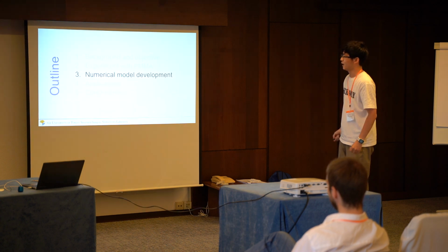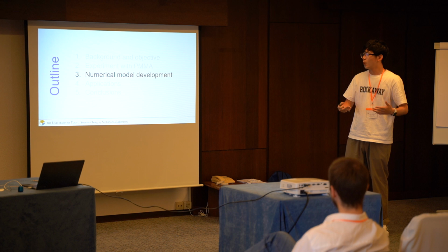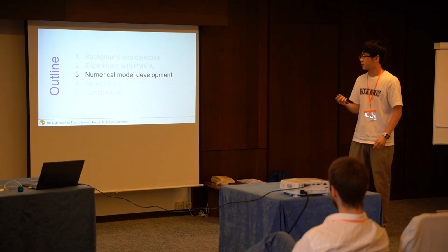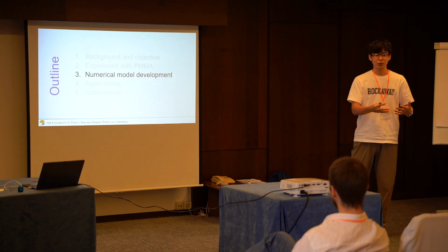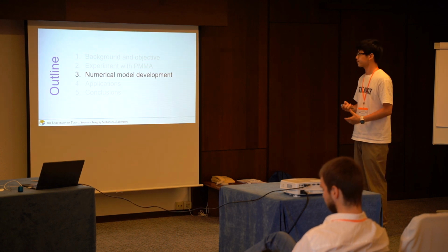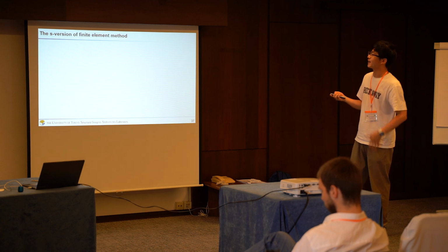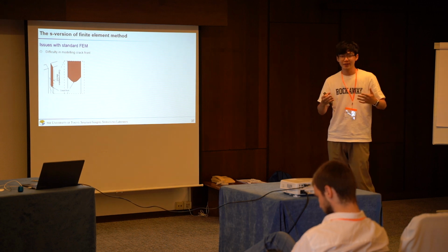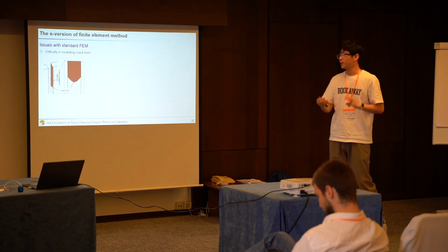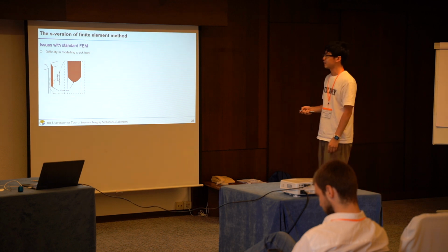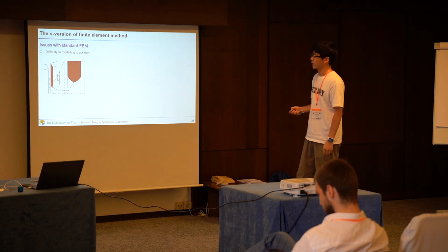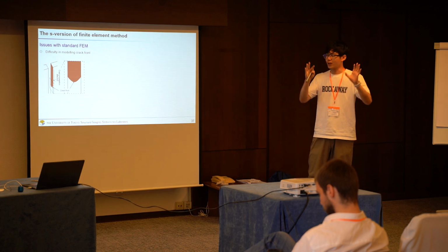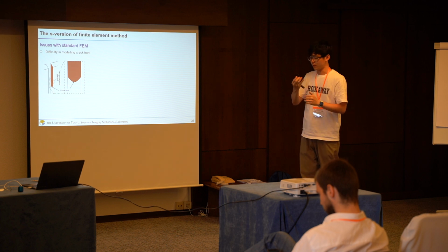And next. Yeah, based on those experimental results, we can start the crack propagation analysis. And next, I will introduce some strategies we used to establish the numerical model. Yeah, the S method I already introduced before, right? If we use the standard FEM to establish our model, there will be two difficulties. The first one is that the shape of the crack front is a curve, so in the standard FEM, it's very difficult or complicated to establish the model.